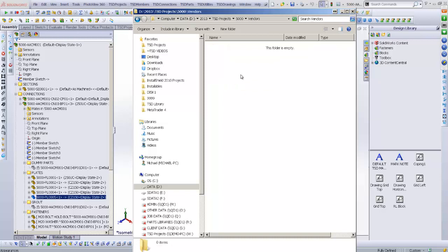Now I pretty much went through a D. You saw a D in there before, the letter D for dummy component, which doesn't get used. There's also a V and an M. An M is the member that we showed you before for the section, and a V is for vendor items. If you were to drop in a vendor supplied item, it could be, for instance, your bolts, which could be vendor supplied items rather than using a fastener process. You could also drop in handrail components, for stanchions and returns and things like that. That's where this gets saved.